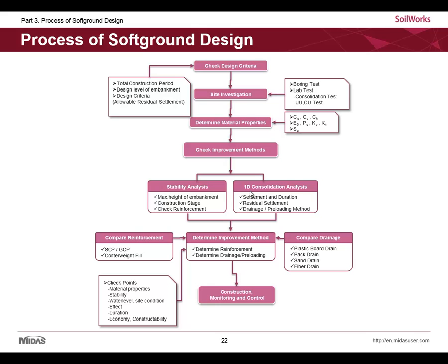So we need to evaluate both the magnitude and rate of settlement of the subsoil so that the settlement in the long term will not influence the serviceability of the embankment. In carrying out the stability analysis, an iterative process is required in the estimation of settlement because the extra fill required to compensate for settlement will lead to further settlement.